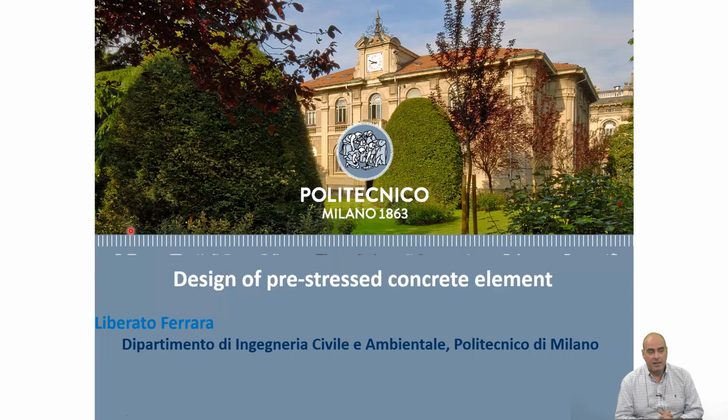Well, there are some examples in practical life of pre-stressing, or even of the alternate of pre-stressing. Barrels are made with wood lintels. That is an example of pre-stressing. You force these lintels inside the steel circles so that they result compressed by hoop stresses, and this gives you the water tightness or the liquid tightness.